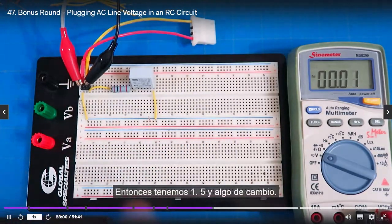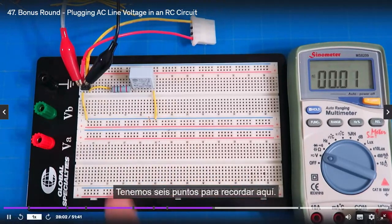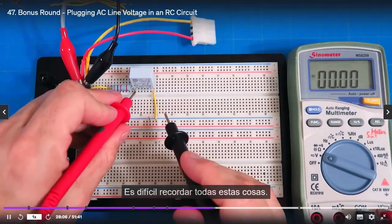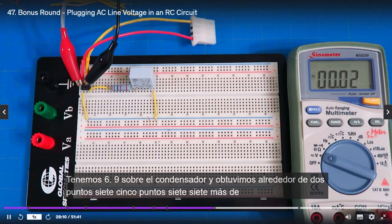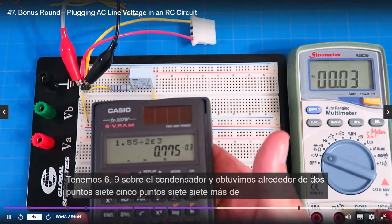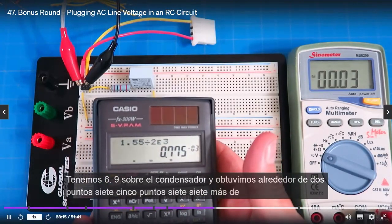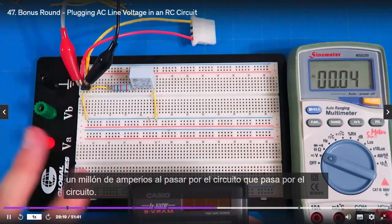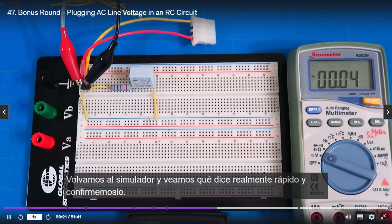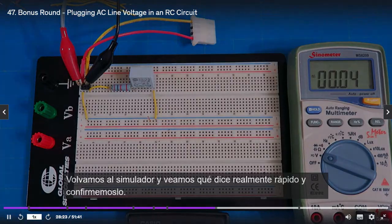Okay, so we got 1.5 and some change. We got 6 point, let's remember here. It's hard to remember all these things. We got 6.9 over the capacitor, and we got about 0.77 milliamps running through the circuit. Let's go back to the simulator and let's see what it says real quick, and let's confirm that.